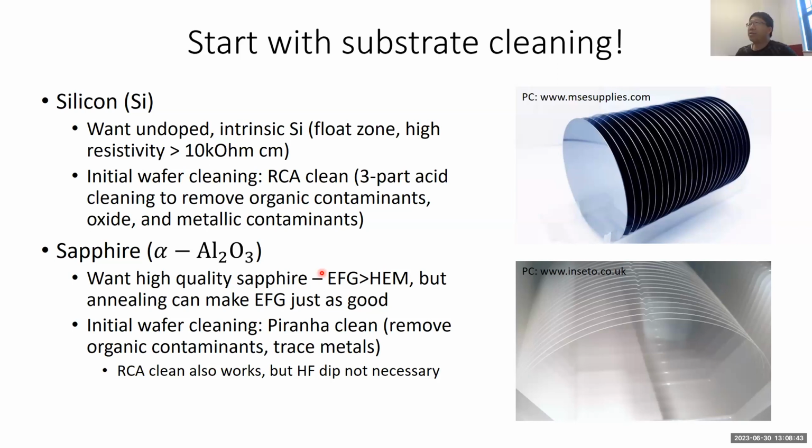Are there any references on this annealing process and documentation of what it does and what kind of good effect it has? So there are several papers that talk about sapphire annealing for the purposes of surface reconstruction. To the point where if you do AFM on the surface of the sapphire, before and after annealing, you can clearly see a difference where after annealing, you can observe monoatomically flat surfaces and things like that.